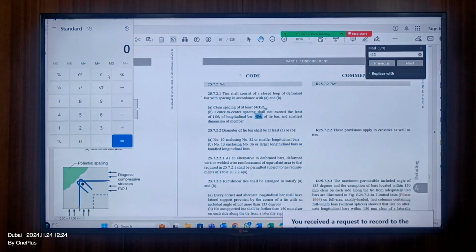But what people used to do, because we have seen it in the shop drawing, that's what I'm telling you, they will follow the same diameters, same spacing: 100 millimeter spacing, 100 millimeter spacing. This is two kinds of things. Either you are literally wasting the rebar, unknowingly, or you cannot substantiate technically whatever the consultant says you are following, or whatever the DM inspector authority says. Sometimes it is a very difficult thing.